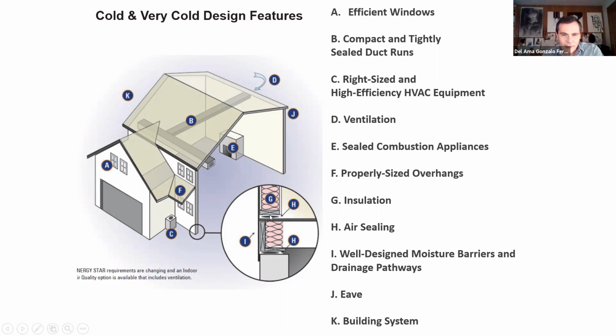You see that here in the connection between the floor slab and the wall, we have this element, which is the air sealing. There might be a crack, and then the warm air can go out through this crack. So we need to seal especially connections between walls. Corners are weaknesses, as are the connections between slabs, roofs, and walls. We need to seal all these elements.